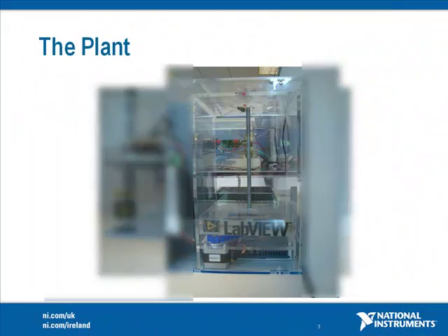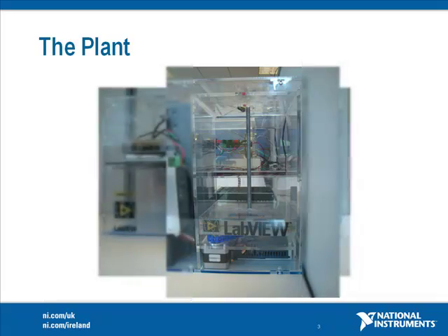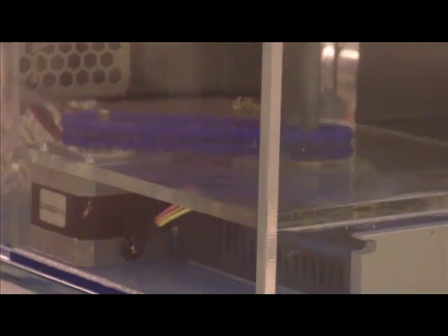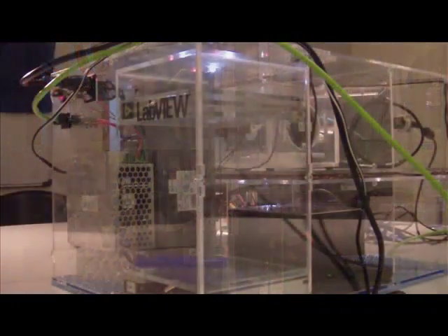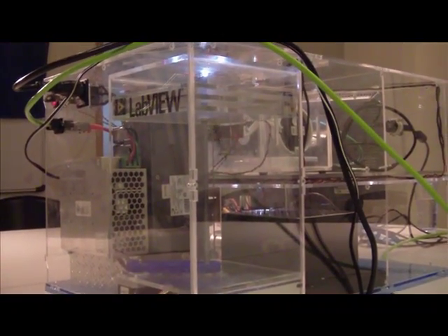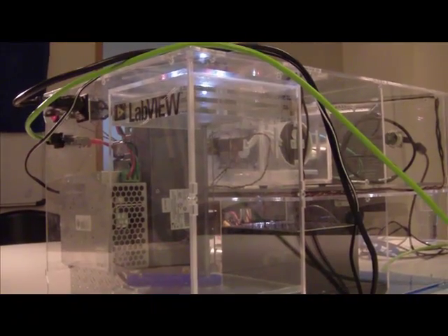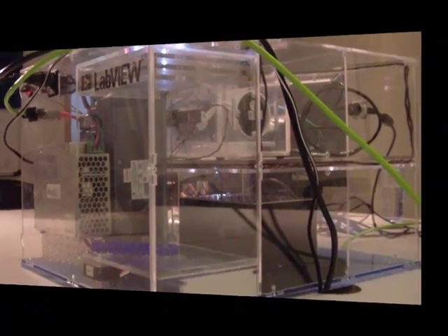In the lift section of the plant we utilised the FPGA with a single C-series digital module. This digital module was used to send commands to the stepper motor drive, telling the stepper motor drive which direction and which speed to travel in. We also closed the loop using limit switches so we knew which position the lift was in.